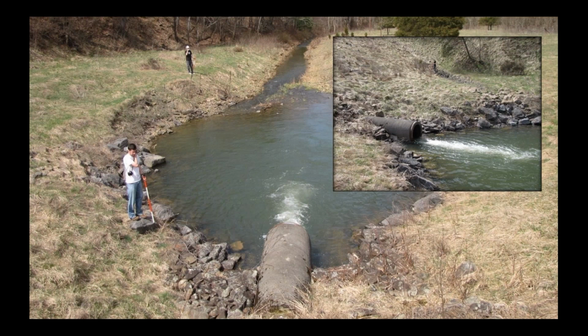In other cases, an impact basin may not be needed. For example, if at the toe of the dam there's good bedrock or a nice deep plunge pool, you can simply have the outlet of the pipe discharging into the plunge pool like you see here.